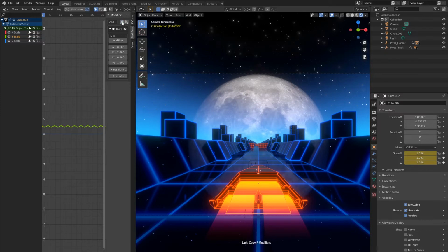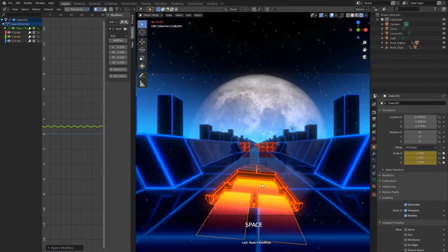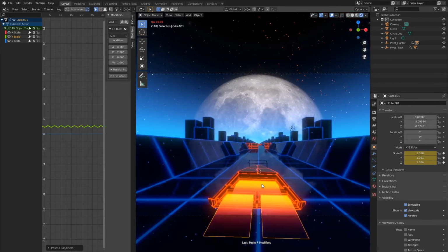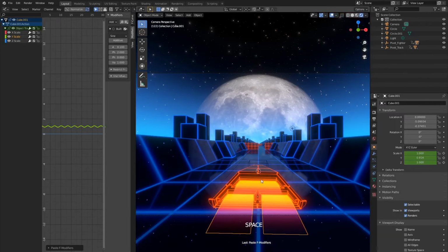Now we can use that copy modifier button I talked about previously. Click it to copy all the modifiers data. Select the second exhaust object. Select the E-scale channel. And click paste modifiers. Press space to play the animation. See how the exhaust jets are vibrating now? Cool. Time to animate some camera properties.